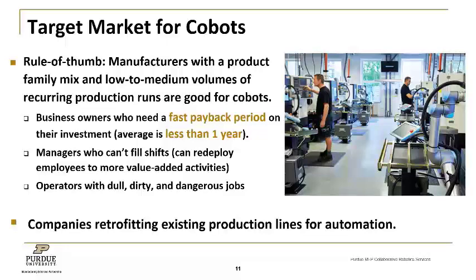So if you have a production volume that you're going to be running for several days on one part, but then you're going to switch it over to another part and then run a similar amount of volume, that's where cobots can usually come in handy and be well adjusted to handle that volume. That's when you really get the return on investment, being able to keep that cobot running versus having to switch it over to do different parts.